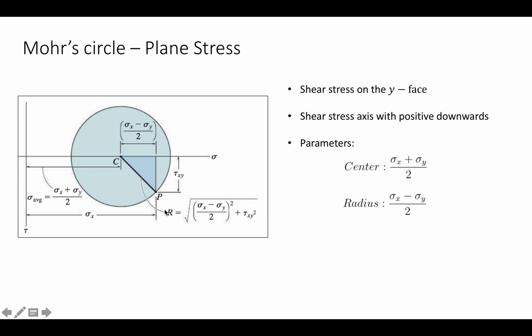You have the radius that you have here, but when you have principal stresses, the shear stress is 0, and then you have exactly this equation. They are basically the same. And then you can find the maximum shear stress, which is equal to the radius, and it'll be found up here in the Mohr circle.